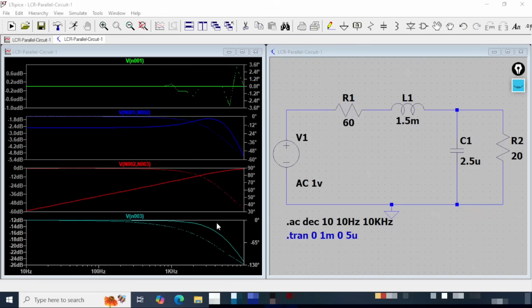Now it is the time domain analysis, and when we come to this particular AC analysis, we come to the frequency domain analysis. Here we vary the frequency and see the response of both the amplitude and the phase. In the previous case the amplitude and phase were also there. Here we see how the amplitude and the phase response change if we have a small signal input and its frequency is varied. This generally we do with a signal generator in practical laboratories where we use breadboards and physical components, right? Here we are doing this.